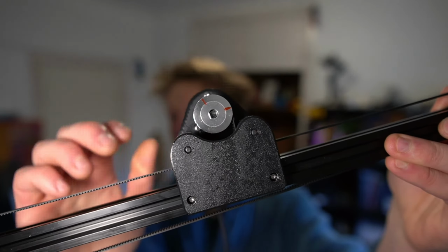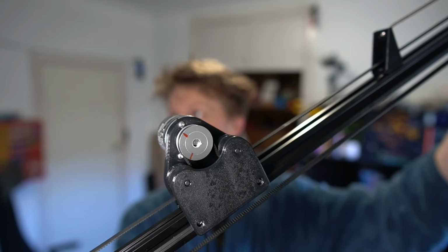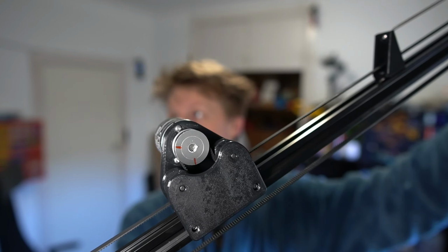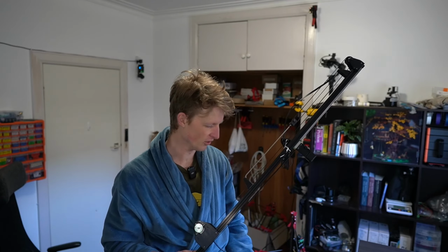The reason for that is because as this spins, it's really hard to hold this still enough. Honestly, it's a lot better now than it was before. But without that shim, the wheel was very clearly a little bit eccentric. It wasn't perfectly centered on the encoder, which is a problem because it means that the belt is traveling with a slightly different radius depending on the position that it's at, which throws everything off.